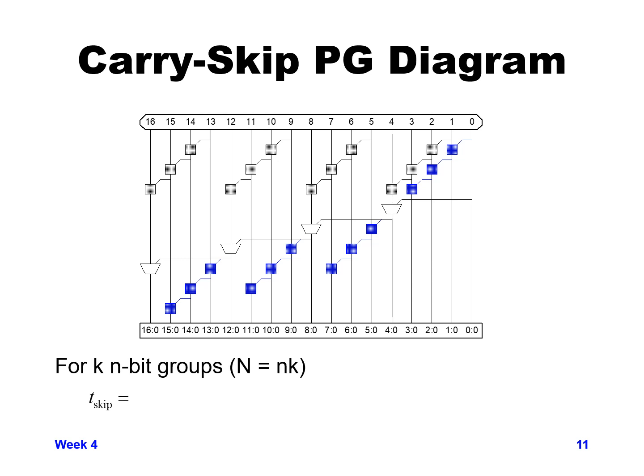That value is waiting for us, so it's basically the delay coming through from bit 4 goes straight through that white box at bit 8 and then goes to the left and hits bit 12, and at that white box at bit 12 we now have 2 potential choices to get to the end. One is the white box at bit 16, but that is a shorter delay than going through the final 3 bits where we have to calculate the carry propagating through bits 13, 14, and 15.